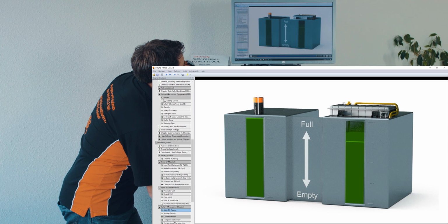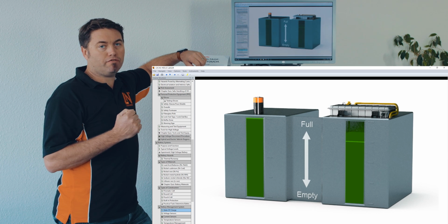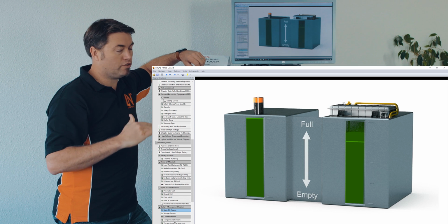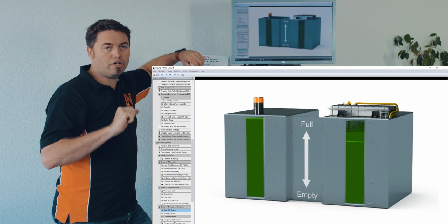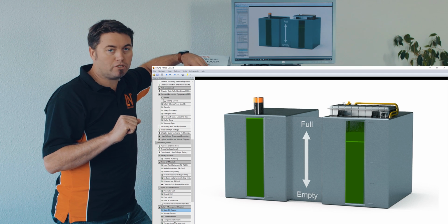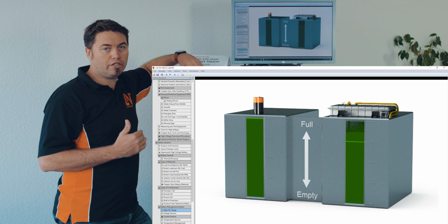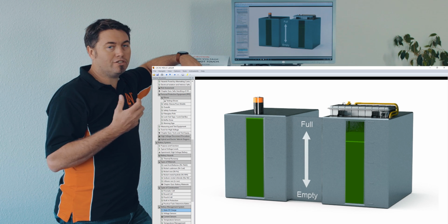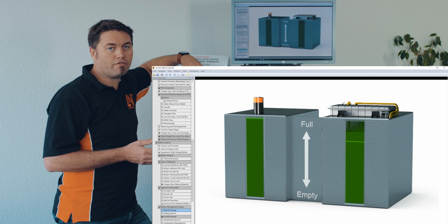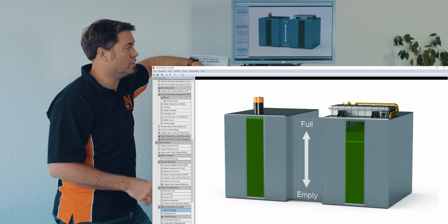we're operating in a very narrow band. So we're not completely using the capacity of the battery. We're not starting to fully charge to fully discharge. We're operating within a very narrow band, roughly between 50% to 80%. Again, every vehicle might be slightly different, but that's to ensure that the battery is not being overcharged or undercharged or discharged, which is going to greatly affect the service life of that battery. So this is what manufacturers are doing to keep the batteries lasting for 10 years or more.